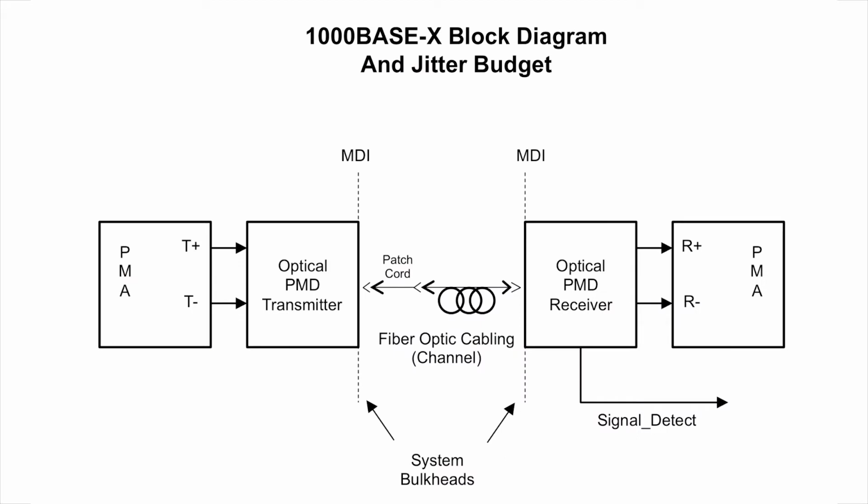The IEEE 802.3 covers in-depth physical and logical requirements for building these interfaces. In this demonstration, we are going to focus on the RX and TX jitter requirements. The diagram shows that at point 1 of the interface, TJ, or total jitter, is 0.24 UI.